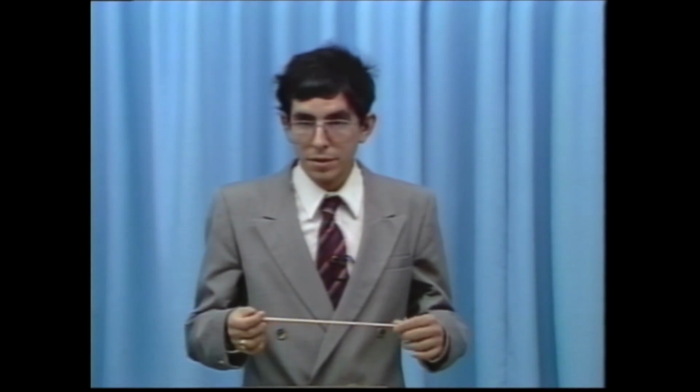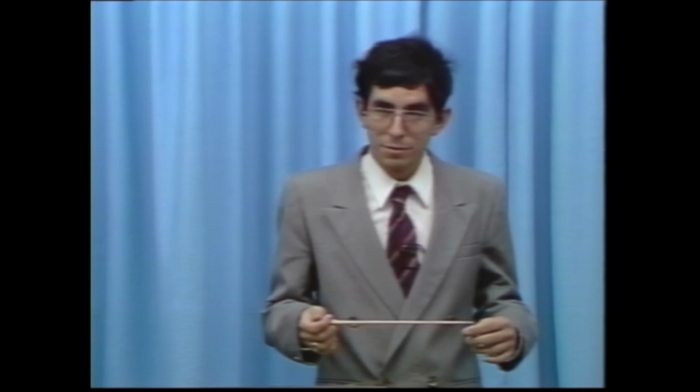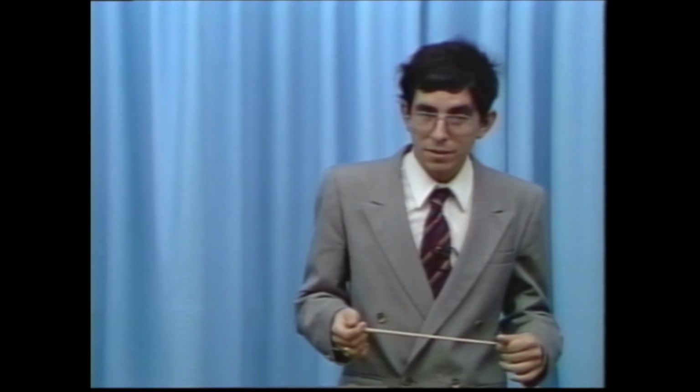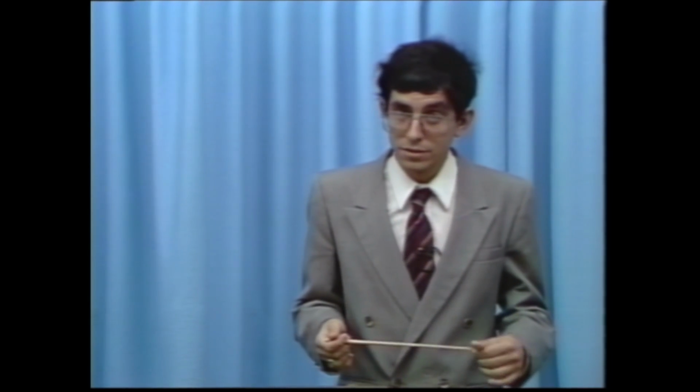For a variety of reasons, you would like the flow to be laminar on the forebody, less frictional effects. You'd like it to be turbulent inside the engine. So there's been discussion about how you try to trip that flow. Imagine, though, a boundary layer trip which has a Mach 25 flow passing over it. One would suspect that the boundary layer trip wouldn't survive very long.